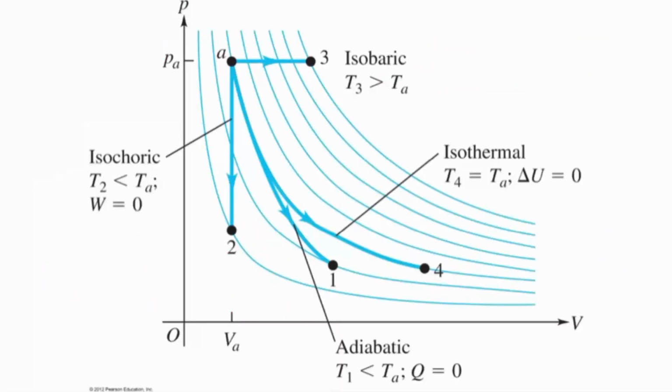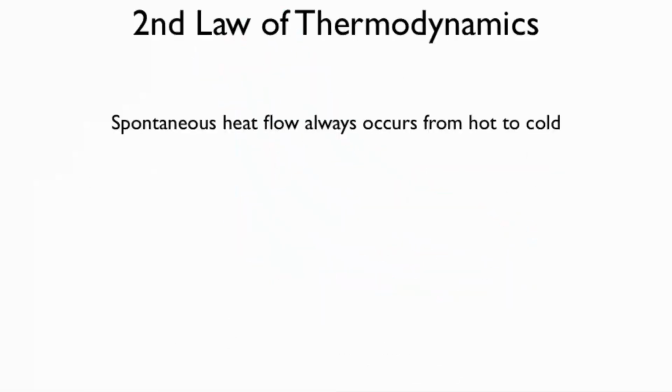This is a picture that's supposed to show all four of them happening at the same time. Basically, it just causes panic in me. But I hope you can see here, if you look at this one, you know that's a constant volume process. Not because they labeled it as such, but which way is it going? Perfectly vertical. Perfectly horizontal would be the same pressure. The one that follows the isotherm is isothermal. And the one that's just doing whatever it wants is the adiabatic process.